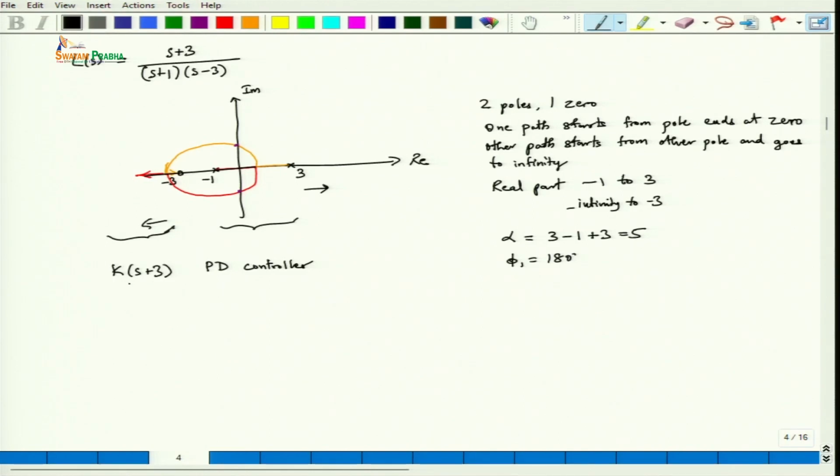But a derivative gain by itself, the proportional derivative, is sometimes not ideal, because the derivative can amplify the noise resulting from the sensor. So in that scenario, what we do typically is we use a controller of the form, we divide this by s plus p, where p is the pole of the controller parameter, which we need to decide based on the specifications.